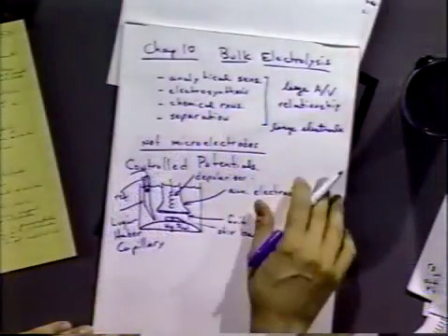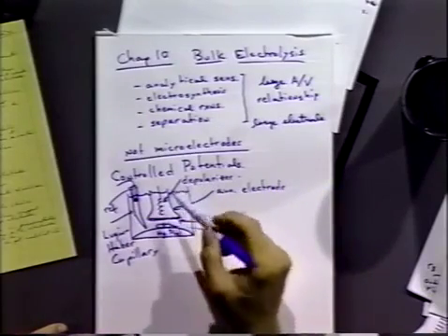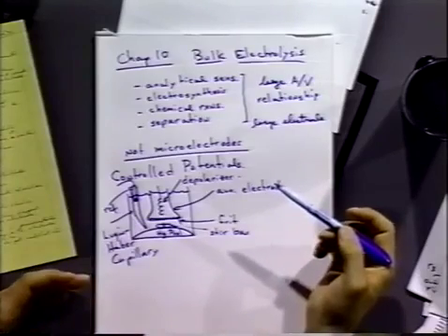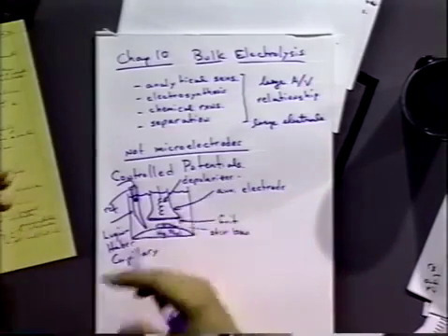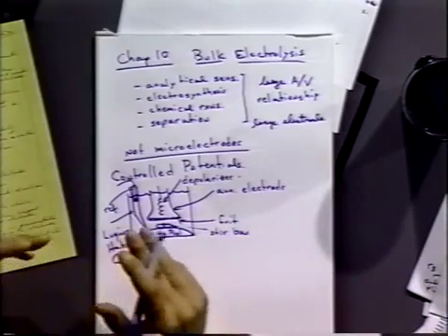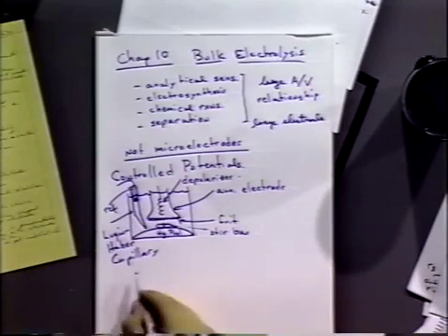Also the problem with the potentiostat is that we need to be able to supply high currents, and in order to supply high current, sometimes we need to supply high voltages to do that reaction. So potentiostats for bulk electrolysis often have 100-watt or even 200-watt capabilities. They can supply large amounts of voltage and current to do it, which means they're actually quite lethal if you're not careful about using these experiments properly.